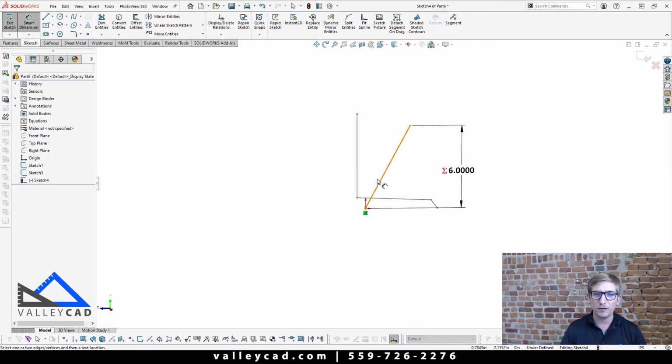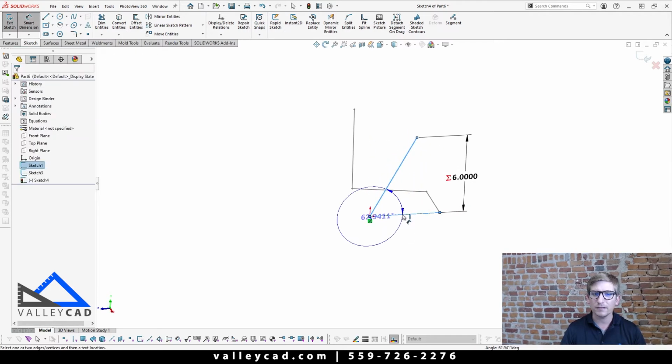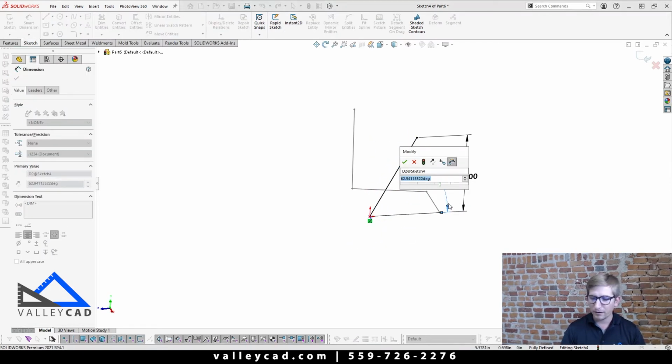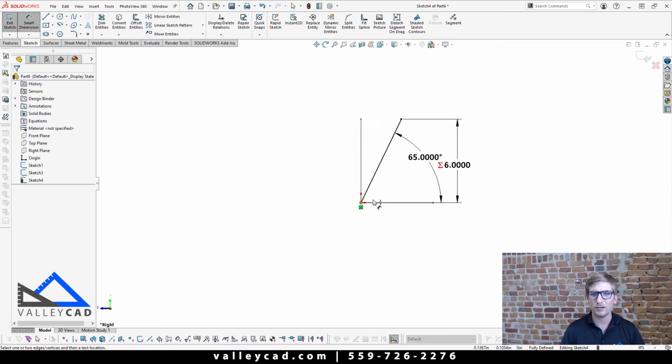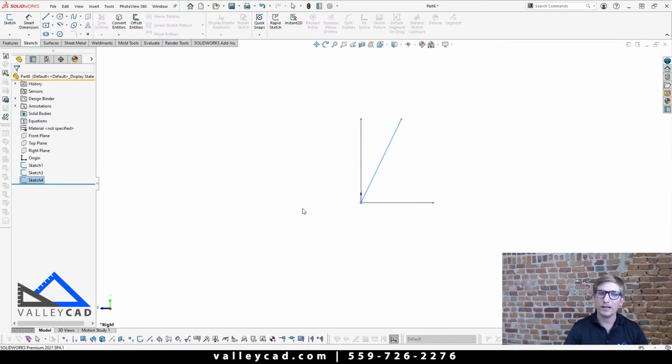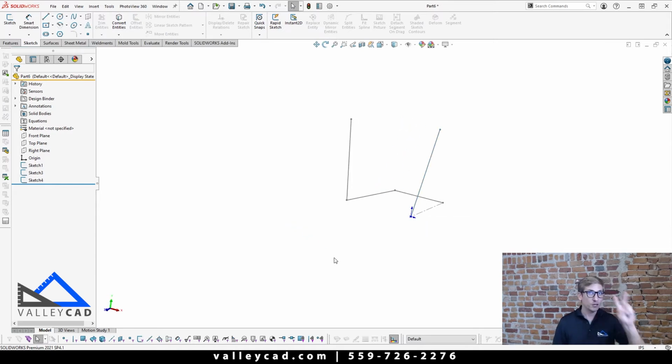So as we look at this, I believe it's coming back at, 65, maybe 70 degrees, give or take. And so what we're gonna do here is grab that guy. We're gonna grab our existing sketch into there, and we'll make it so it's 65 degrees back, just for this given scenario here. And we'll simply say okay to that. Okay, 2D sketch is made. We made 2 of them too. This is where we now take the 2 2D sketches and we make a projected curve from it.